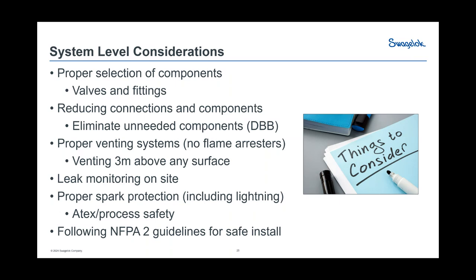The problem is, and what we've seen is, some of these 1-inch valves that I mentioned earlier had absolutely massive air actuators on them. They were the size of a small garbage can, and they were putting so much load onto those poor little needles that they were getting very, very low cycle lives, 15, 20 cycles before they would wear out and break. They would just deform the material so badly in order to make a seal. So again, getting up into the larger sizes can lead to problems of getting valves to seal.